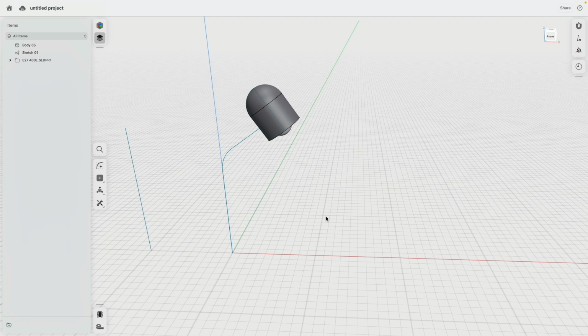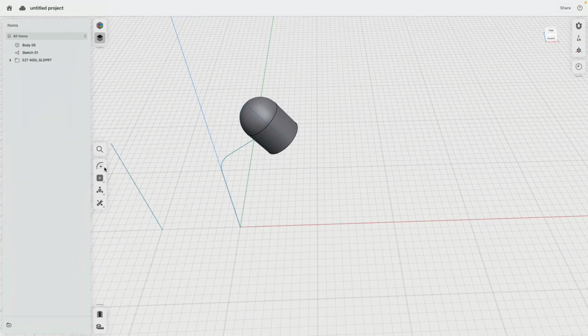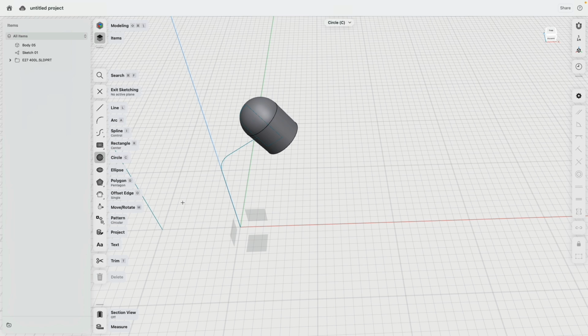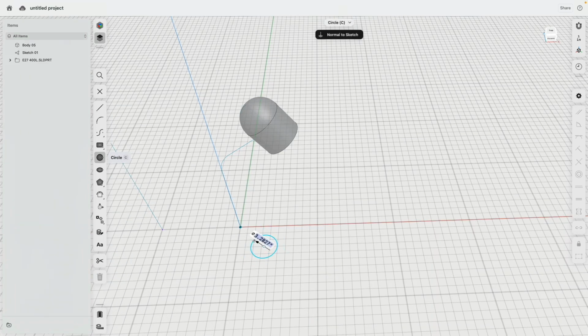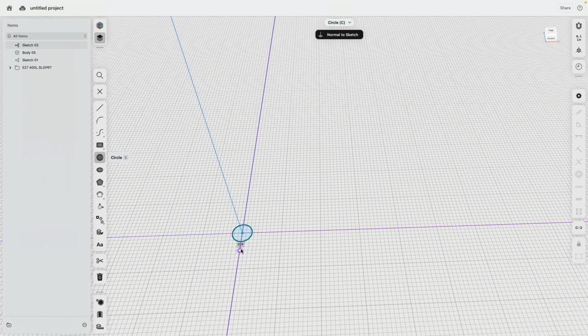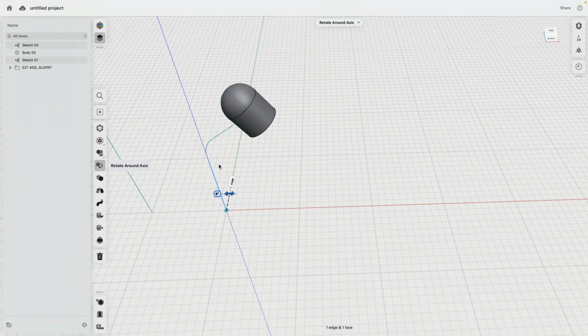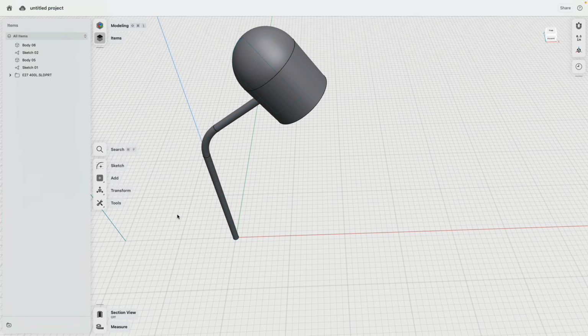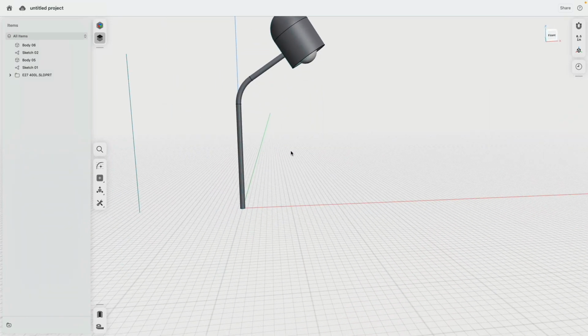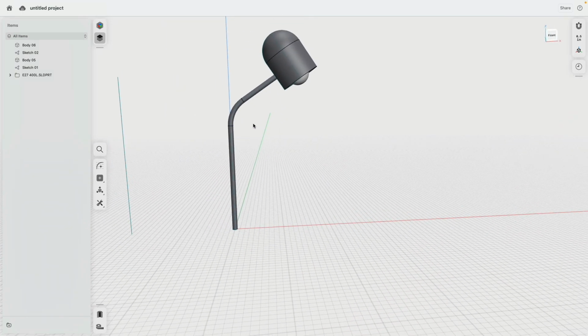This was actually the most complicated element we needed to design. We can then start thinking about the base and also how the pipe is connected. Maybe I'm going to do the pipe first. This is here on the ground. This first line was on the x-axis, so I draw 1/2 inch of a pipe, and then I sweep that one along there. There we are. Very good. Yeah, that feels good.